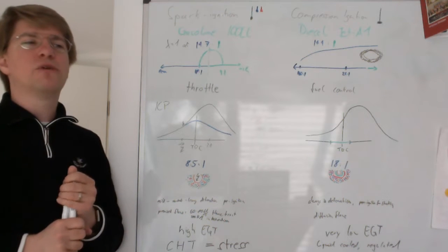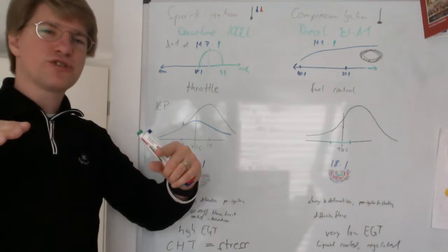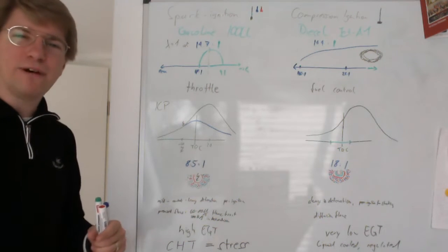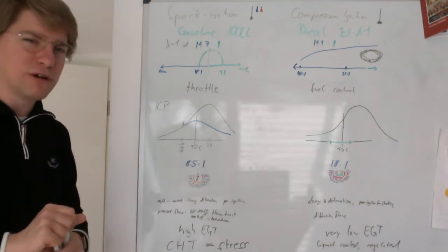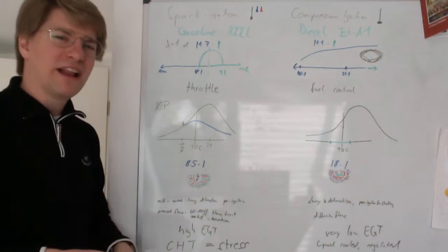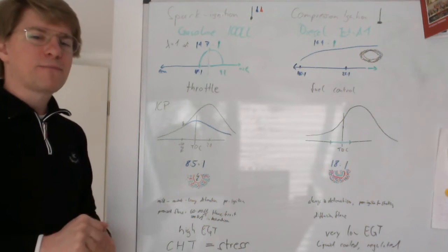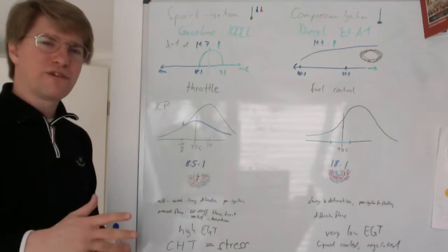We like to cruise at altitudes that lower the ambient pressure so much that we can just leave the throttle valve fully open, and we get like 24-inch, 23-inch manifold pressure at full open throttle. And that is the most efficient way we can run our engine, because we have no losses from the throttle valve.